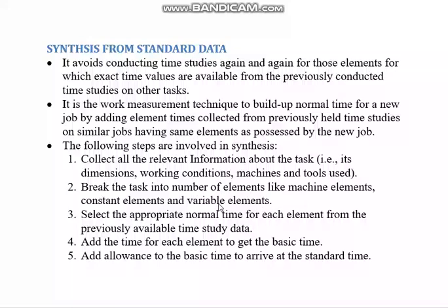And then break the task into a number of elements. Then select the appropriate normal time. How are you doing it? If you are taking previously available time study data, then that is synthesis from time study.